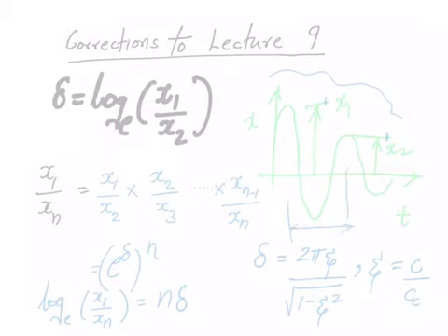In practice we won't be able to measure such a very short duration of time. So mostly what we do is measure the first amplitude, then wait for, let's say, n cycles, and then measure xn. If you know x1 and xn, we need to compute your delta. So we will go about doing that like this.